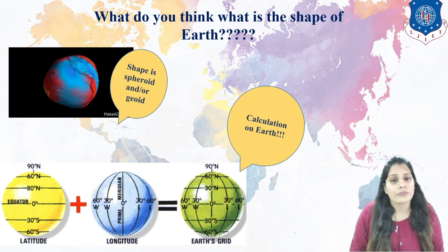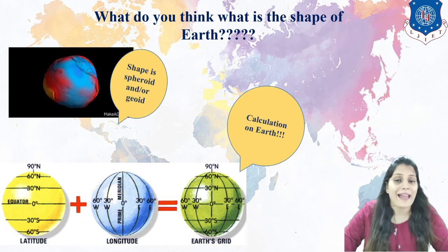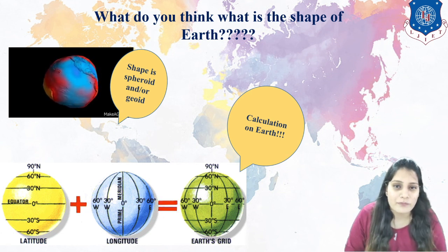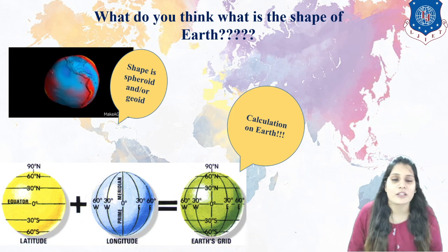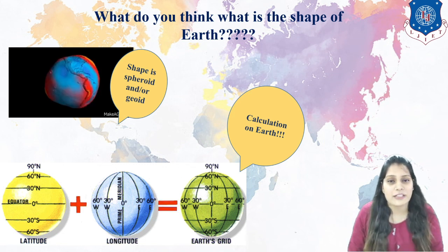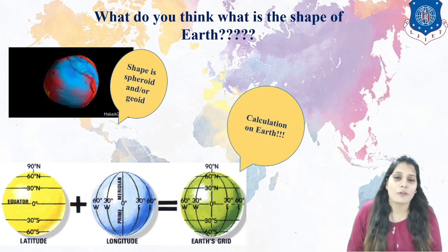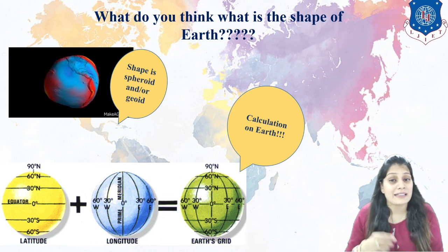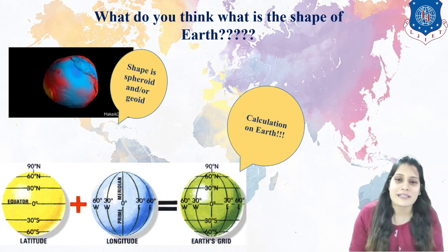So what do I have to do? From the globe, I have to convert to flat. And that is why I have to provide the coordinate systems. And there are a number of coordinate systems and projections. We are going to see that also in detail, with reference to what the shape of the earth is, how latitude and longitude work, how we have collected the data, and what the accuracy of the data is. So this is the accuracy of data.